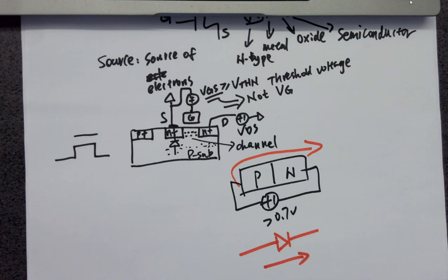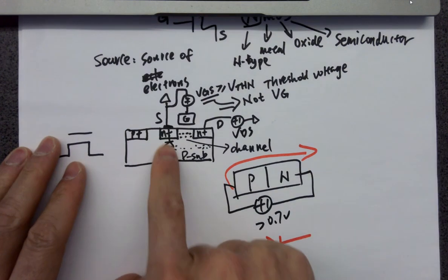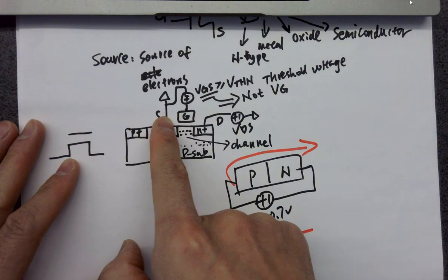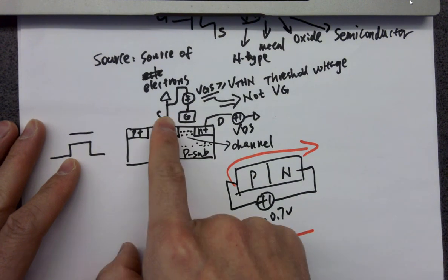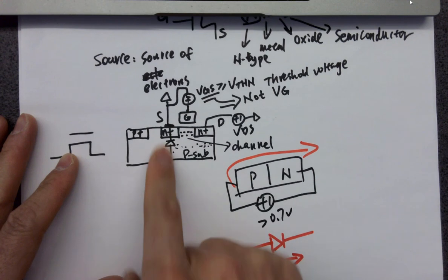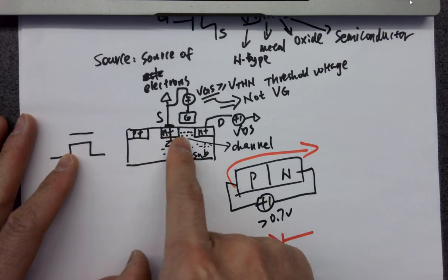You got a voltage on your ground, yes. For example, the P sub, right? The P sub is like one volt, and the wafer itself is 1 volt, and your source is grounded. So N-type semiconductor material is grounded. So in that case, it's forming a diode, and it's being forward biased because the P sub has a higher voltage. So what's going to happen is it's going to flow a current into source, and eventually it flows into the channel.